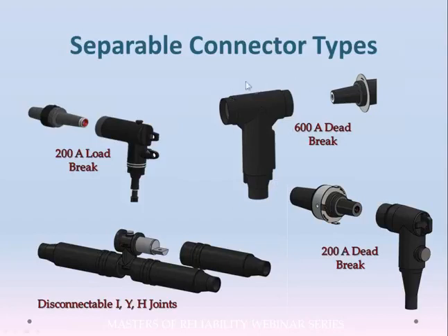And then finally, for this T-body, the 600 amp dead break elbow, there are many accessories associated with all of these connectors. But there's one accessory in particular, what we call a connecting plug, where you can stack two dead break elbows together, and that's a joint or splice configuration. So there is a precedence to say why this joint should be in 386.